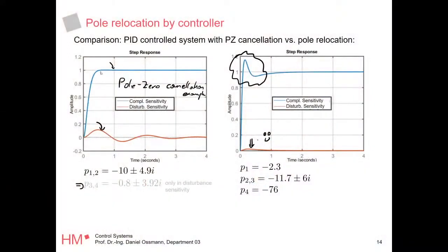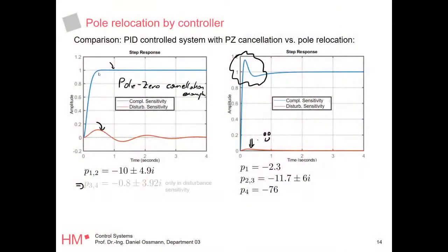The blue one results from a command input. Let's think of a car. When the pilot is doing something, he gets a lot of overshoot. However, we know when the pilot is doing something. We can measure that. Usually in digital control systems, X by wire for example, when the driver turns the steering wheel, the computer knows that. So you can change that signal and make that better. On the left-hand side, this is perfect, no improvement there, but you cannot change this one because you don't know the disturbance.